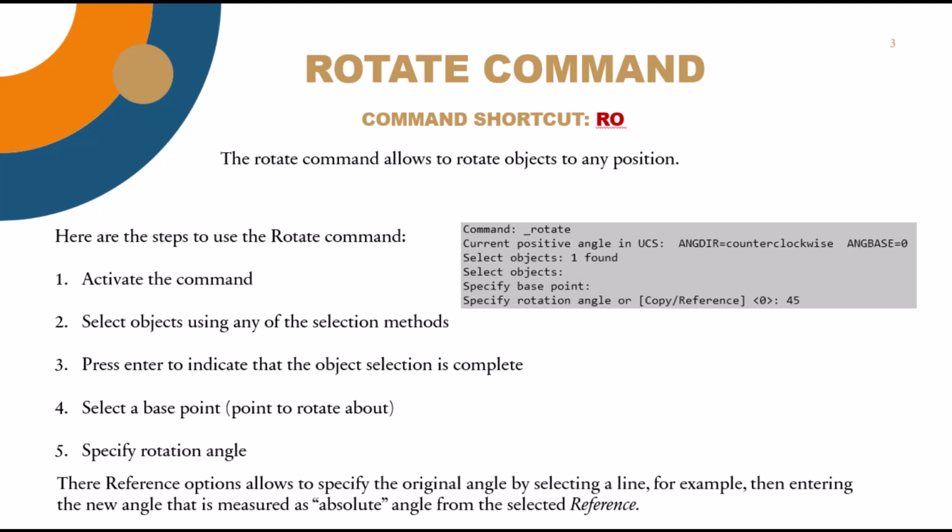Then you have to press enter to indicate that the object selection is complete. Then you select the base point, which is the point you're going to rotate all these objects about. And then you have to specify the rotation angle.